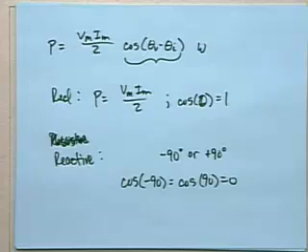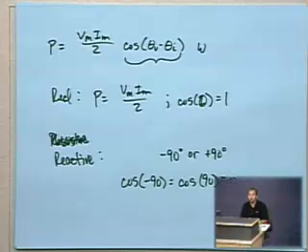So that's average power. Now, normally our circuits are not going to fall nicely into just one of these two categories where it's entirely real or entirely reactive. And so what we're going to have to do is find out the relationship between the voltage and the current as a result of the combination of circuit elements that are there. But I could ask you, what is the average power absorbed by an inductor? And the answer is 0. It has an average power, and that average power is 0. That's what it happens to be. So how do you calculate that?